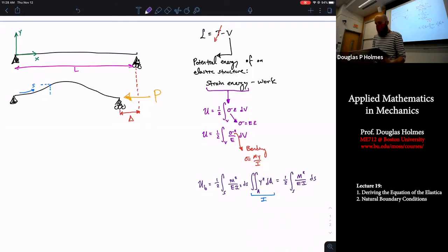And there's a constitutive law that relates the applied moment to the curvature, and it looks like this. The moment is equal to the curvature at any point along S. Now what that means is that we're not assuming that our curvature is uniform along the arc length, which is definitely a good assumption. We don't think it's uniform, right? I mean, clearly there's like an inflection point where it's curved this way here, and then curved this way, and then curved that way. So kappa is definitely changing as you go along S. So kappa is a function of S. And then this is also multiplied by EI.